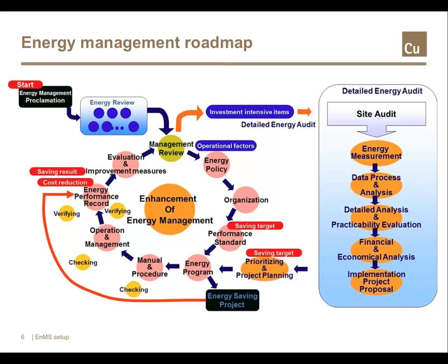Next, the top management establishes an energy policy, appoints an energy manager, and organises an energy review to identify energy conservation opportunities. Based on the results of the energy review, the first management review establishes an energy baseline and energy performance indicators. Acting on energy conservation opportunities, or ECOs, is authorised within an energy programme, or they are earmarked for further study if they would require intense investment. All items for action are consolidated and documented in an energy management system action plan. At the same time, the energy policy and the organisation to operate the energy management system are officially launched.